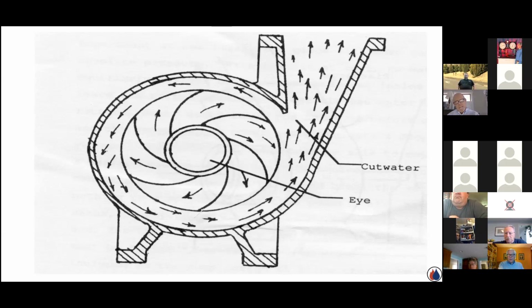It's a centrifugal pump, adds velocity, spins it off the vanes of the impeller. There's all kinds of designs and different diameters, thickness. If you're doing 1800 RPMs versus 3400 RPMs versus 1100 or 1200, there's all different. That's all from the manufacturer. That's all engineering that they get involved with the pump manufacturers. That's their deal, how they build the pumps based on certain applications, et cetera. But the general concept is it's a centrifugal pump. Water enters the eye, gets flung along the vanes, and discharged out the top.